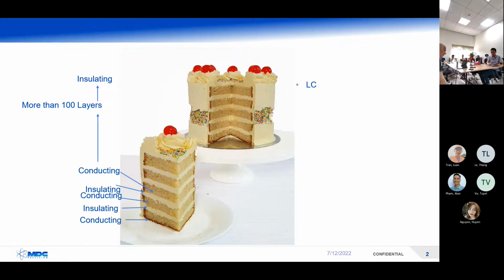Can I ask a question? Yes. My laptop has an Intel Evo i5 chip. Is this over 100 layers? It's probably about 70. But in there, you have a NAND flash memory chip, which has almost 200 layers. If we have time, I can show you a semiconductor circuit that is called planar, which is the old type. It's like a town where everybody has one house, okay? NAND flash is like the 81-story tower in Saigon, right? It builds up.